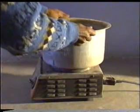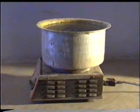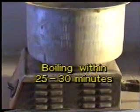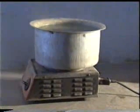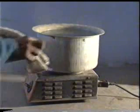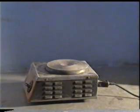At the end of 24 hours, heat the water with assembly submerged at a rate so that it starts boiling within 25 to 30 minutes. This is done to accelerate the slaking of magnesia with water. Keep the water boiling for 3 hours. At the end of 3 hours, remove the assembly from the hot plate and allow it to cool.